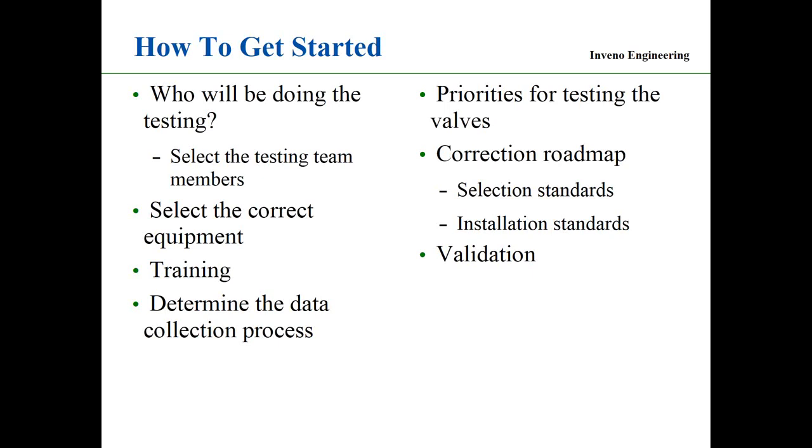Select the correct equipment. Years ago, we used to use screwdrivers a lot. It wasn't too safe because you got too close to the valve. It could be extremely hot, burn your ear. Safety. So today we don't have to do that, but we want to use ultrasonic equipment. Training: what training is required to do the test.